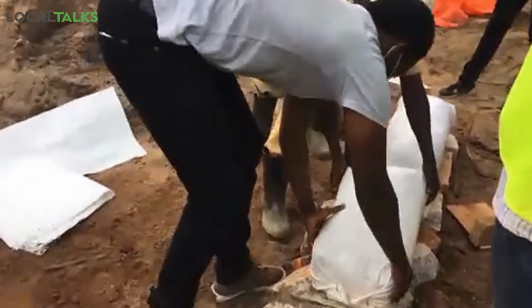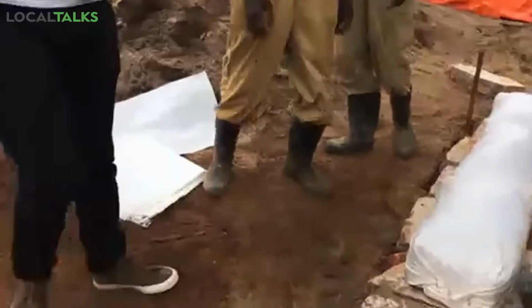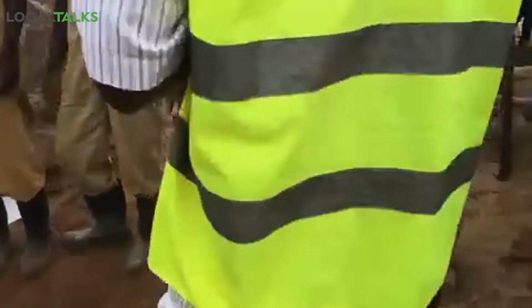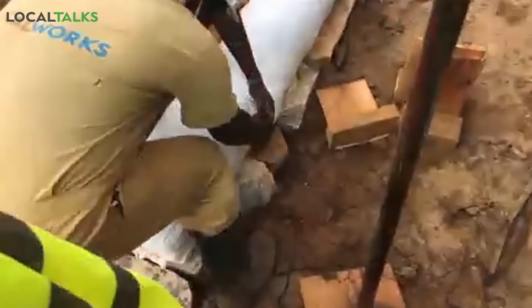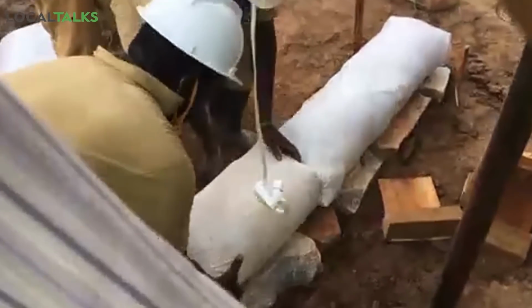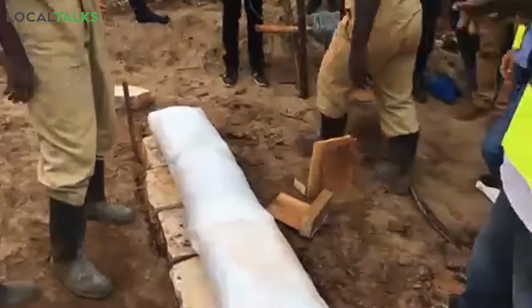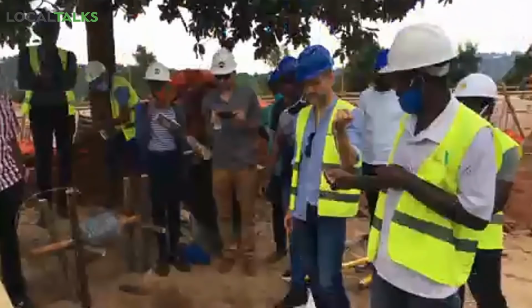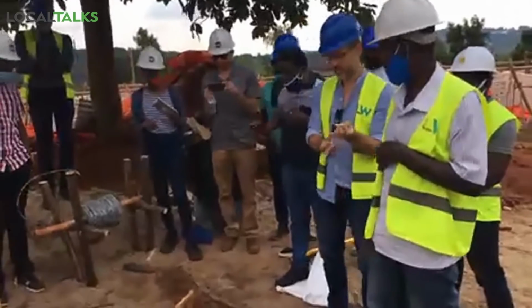Okay. Now we have placed these 3 bags very close to each other, and they are now being compacted. Maybe some guys can first show it, and then some volunteers can try. Maybe one thing to understand is these bags should be close to each other, should be tight. If they are not tight and you leave a gap, that means they are going to increase in length. And we want to maintain the same height we measured there. So I think that's very important.